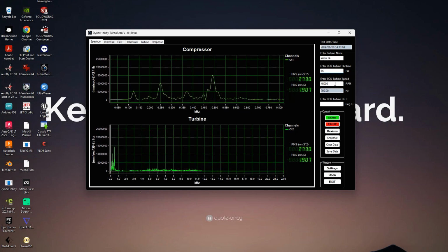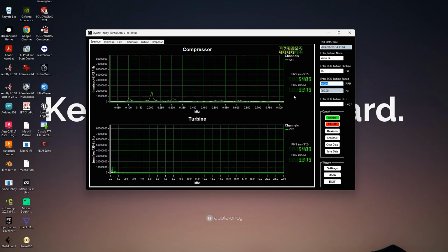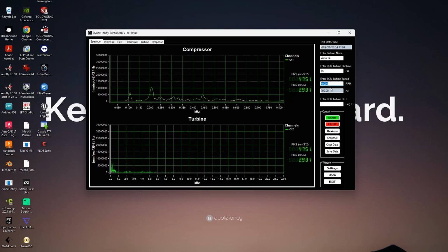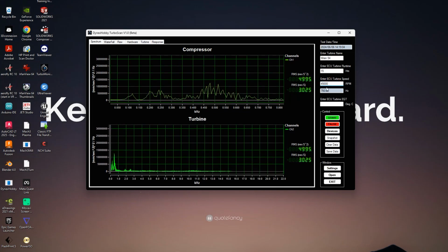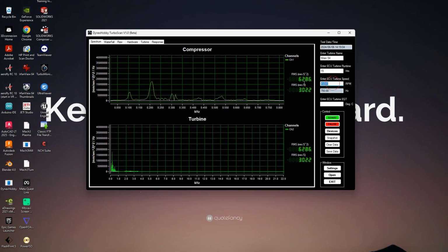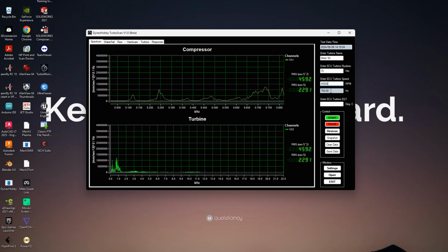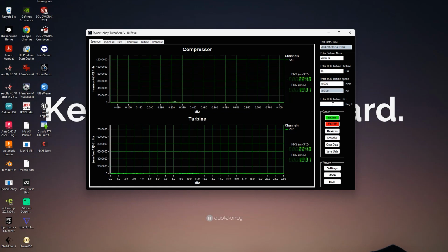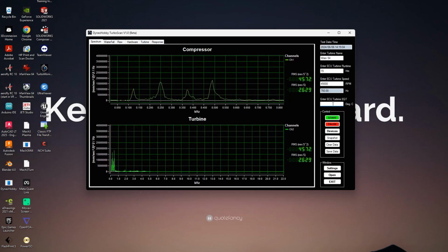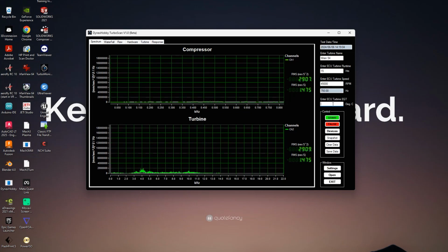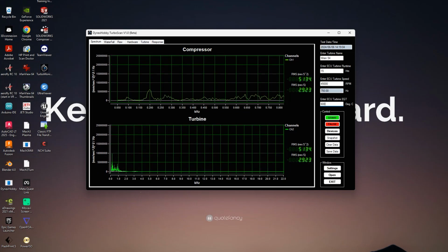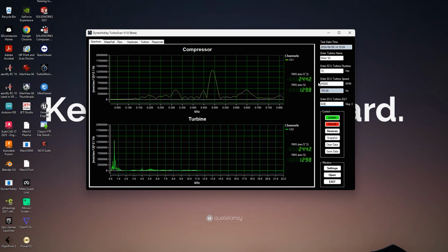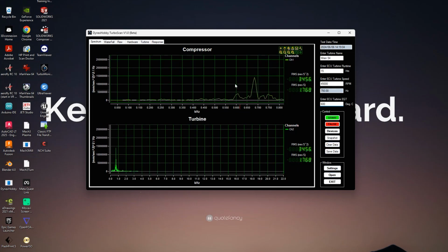And you want to enter the speed of the turbine when you're taking recordings. So let's say, for example, I want to record the vibration roughly at idle. So let's say it's 45,000 RPM. So you enter that. That RPM gets translated into a running speed in hertz. You could also enter the turbine EGT, the exhaust gas temperature. So that might be in the order of 600 degrees, whatever it might be on the day. So that's just an overview on how that works.